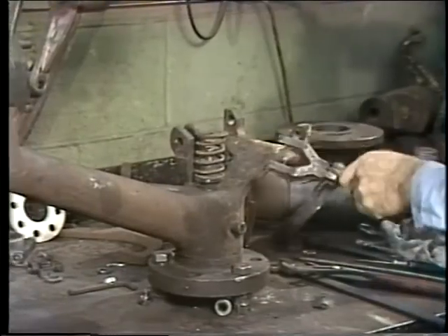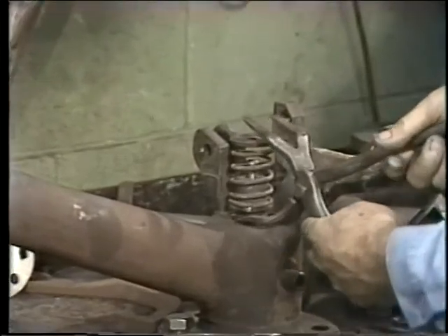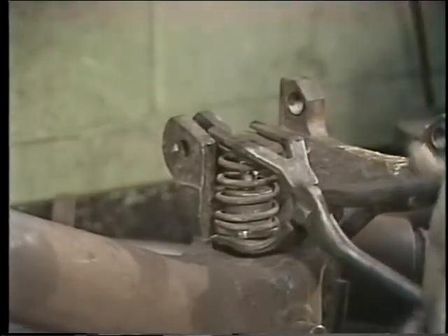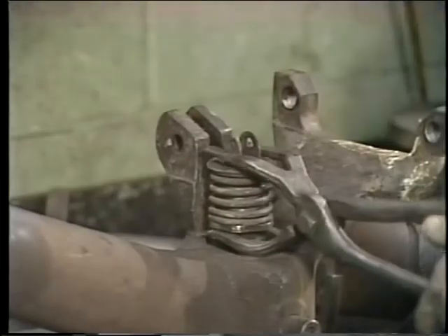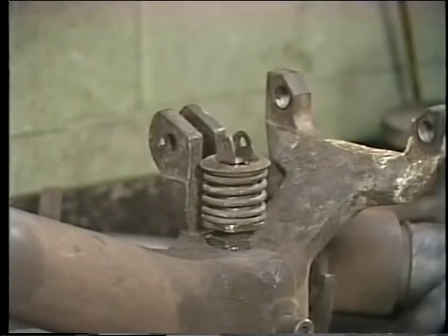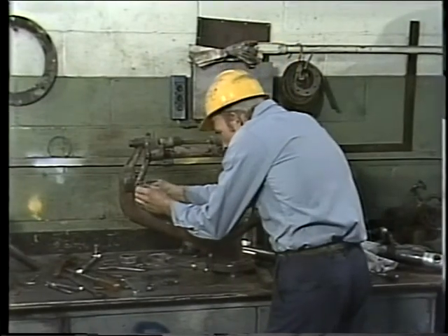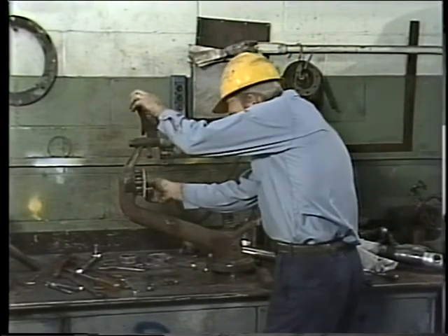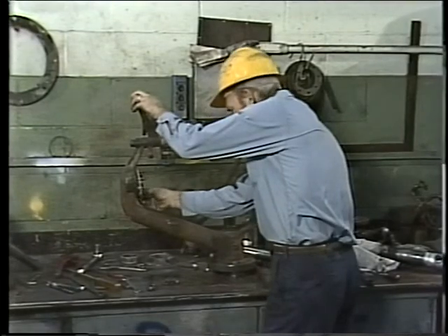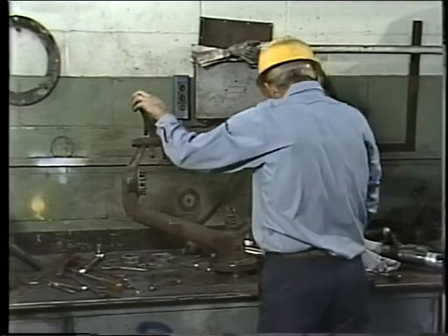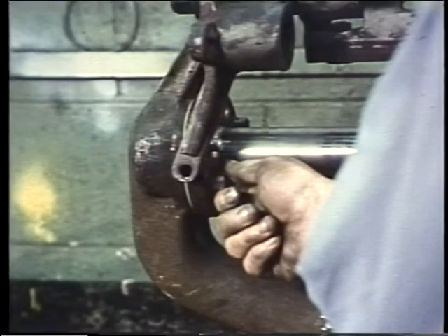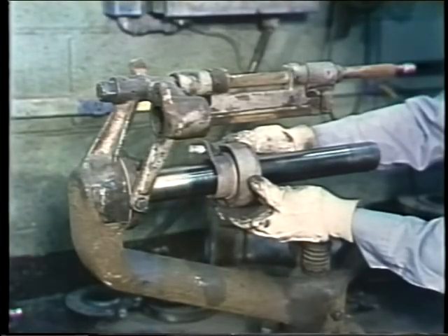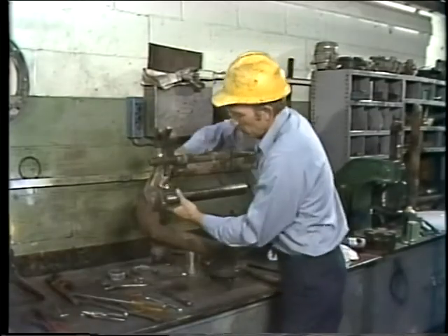The valve spring is replaced using a spring compressor to hold it down, while the keeper is put on to retain the spring. The keeper is slid onto the stem and the spring is released. It's held securely in place. The next step is to replace the feed tube. A new gasket is used. It's slipped onto the flange and the feed tube is held in place while the nuts are snugged by hand. In order to ensure even tightening, after the bearing and its retaining nut are installed, the nuts are tightened with a wrench in a crisscross pattern.